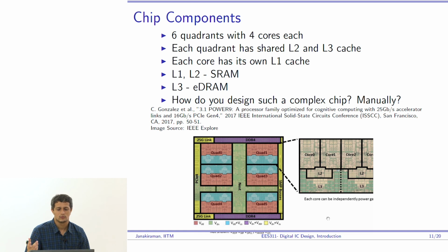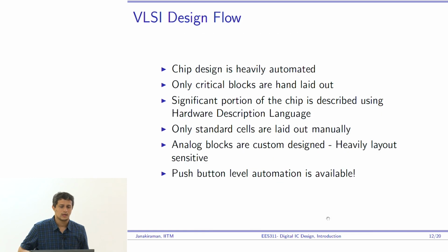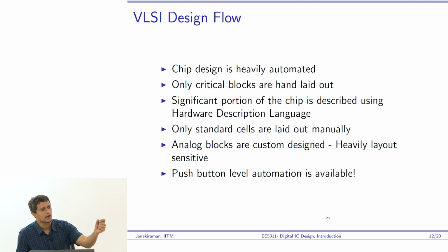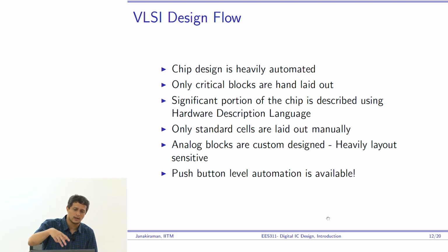And therefore, what do I do? It turns out that the VLSI design flow is heavily automated, right? A lot of this is just you write something known as Verilog code, then you can synthesize and get your layout, right? Layout is basically what you learn in this course, right? The eventual thing that you can ship to the foundry and say manufacture this, right? It's a set of masks that you will make.